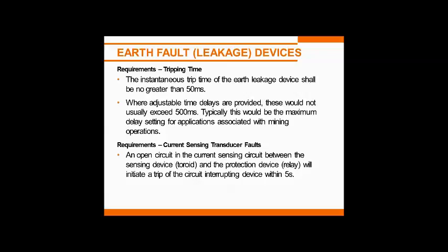Okay, instantaneous trip time. Basically, it's saying the relay must be able to trip in no greater than 50 milliseconds, and typical relays, the VSD guard, for instance, trips at about 36 milliseconds. The ELV relay was somewhere around about 40 milliseconds, so they're well within that requirement.